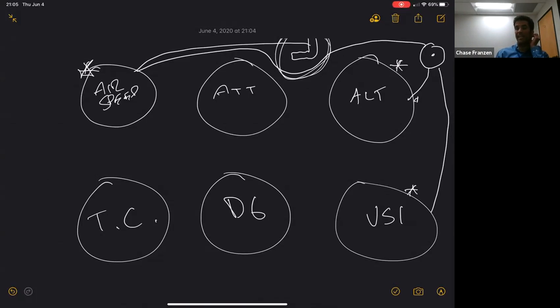So the pitot tube, the ram air port, the mouth, is gathering fewer molecules. It's telling you, hey, we're at 80 air molecules right now, versus at 1,000 feet you might be at 100 air molecules. So that's what the airspeed indicator is indicating: the ratio of the amount of air molecules going into the pitot tube compared to the amount of air molecules that are just sitting statically in the space that we're occupying.